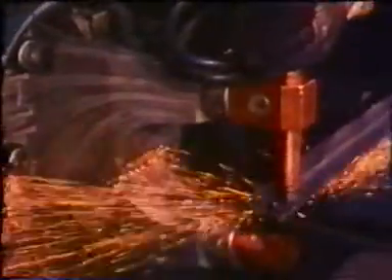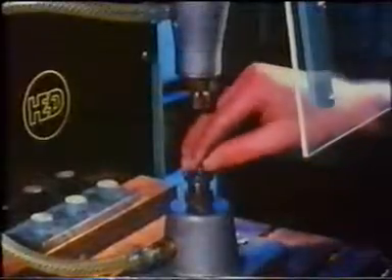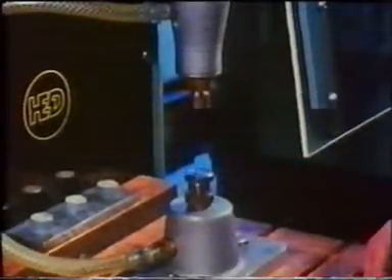Throughout industry, resistance spot welding is used to join a wide range of metals. Because weld times are short, high output is possible. Because only a small area is heated, distortion is negligible and no finishing treatment is needed. And because the method is faster and more reliable, it's replacing soldering for joints on miniature components.